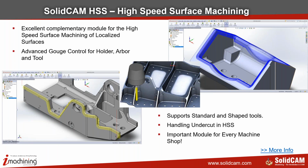And most important thing, if there are undercuts, generally in die mold, there are no undercuts, because if you have them, then the part cannot be ejected. But just assume for the sake of theory that this is not true. For example, if a customer is machining, let's say, shoe molds. In case of shoe molds, undercuts are allowed because the sole is flexible and can be pulled out from there by the hand from the mold. So in these cases, undercuts are allowed. And in this case, if you would like to do undercut machining, then HSS is one of the options, but we do have directly undercut milling inside SolidCAM. So HSS can handle undercuts, but we also have another machining strategy that is designed to machine only undercuts.